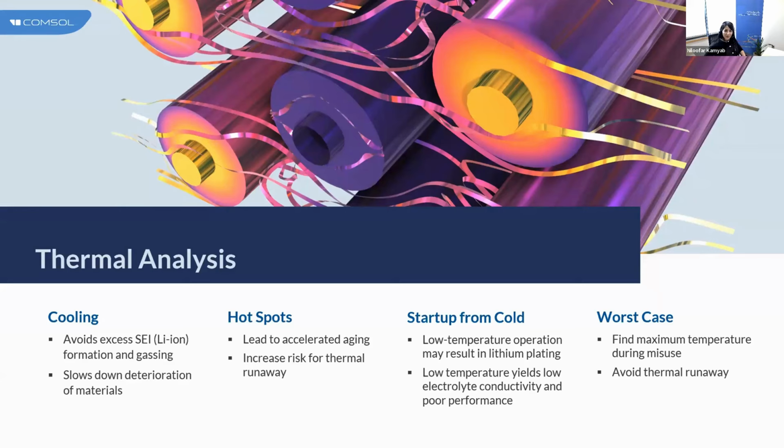So by building a thermal runaway model of a battery pack, you want to know, first of all, which cell goes under thermal runaway first, which cell is next, and the next, the order, and then how much time you get as the entire battery pack goes under thermal runaway, how much heat will be dissipated, and hopefully design a thermal management system that can completely mitigate this. If a cell goes under thermal runaway, you can shut down the problematic cell and maybe you can survive the situation without any catastrophic results.